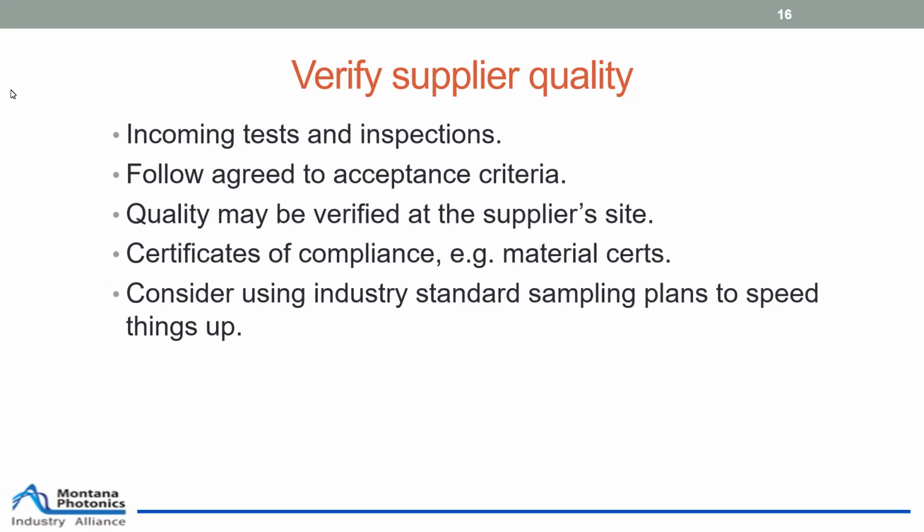Verify supplier quality with incoming tests and inspections, and follow agreed to acceptance criteria. Quality may also be verified at the supplier site, but expect test reports if the supplier does it. Certificates of compliance, for example, material certs, may also be used.